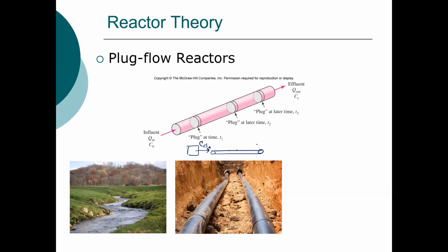So we can model that concentration of chlorine as that water moves through the pipe. And we can use these same sort of plug flow reactors. If you've used, or will use EPANET in 422, there's actually a component of EPANET that allows you to do this chlorine modeling. And it's all based on plug flow.